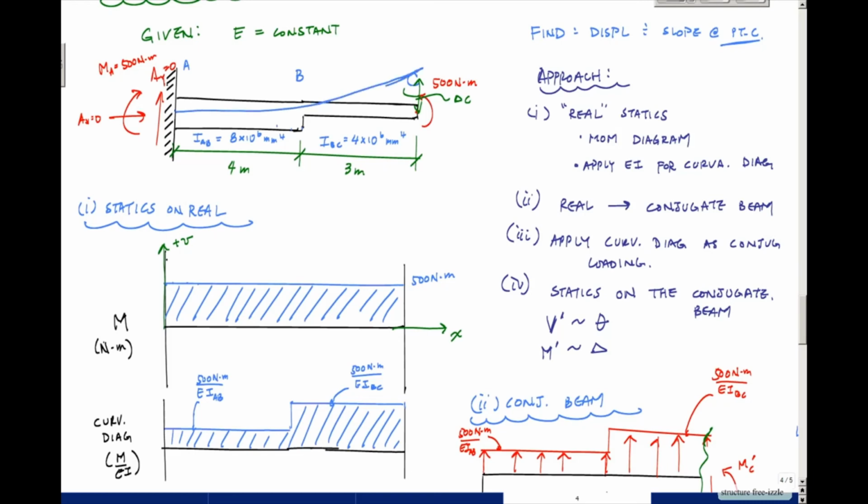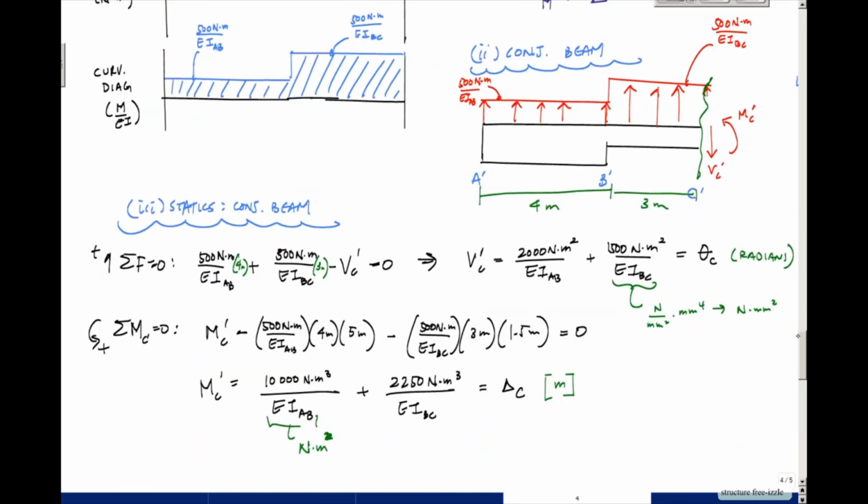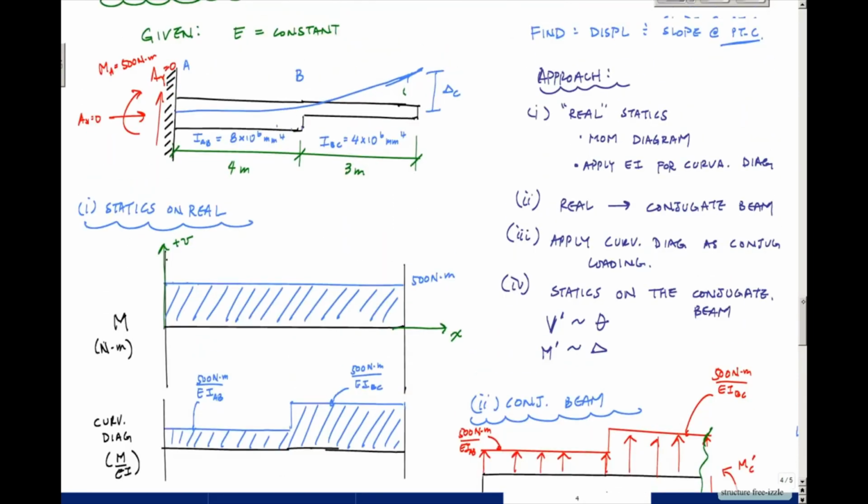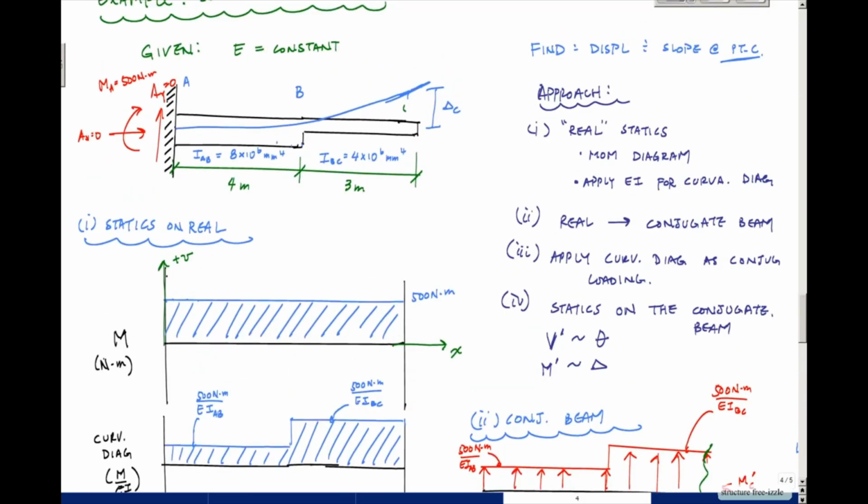Here's this, and this displacement, if I could erase some stuff here from the elastic curve right here. So this elastic curve, due to that concentrated moment at point C here, there's going to be a deflection upwards, delta C. And that positive value indicates this moves upwards. This positive slope, this positive theta, indicates, according to the sign convention that you chose, that this right here is positive theta C. That's this slope right there.